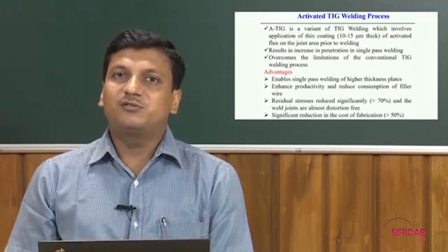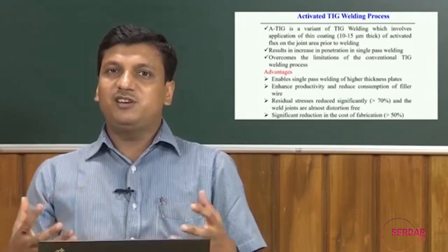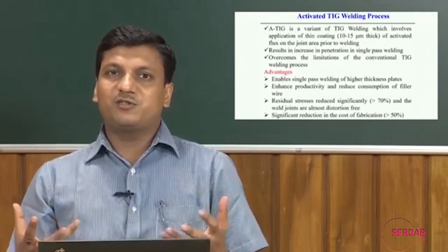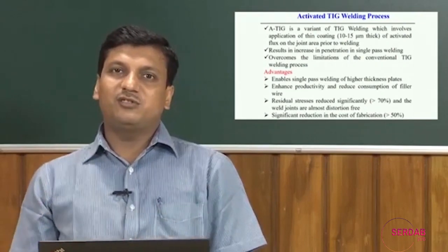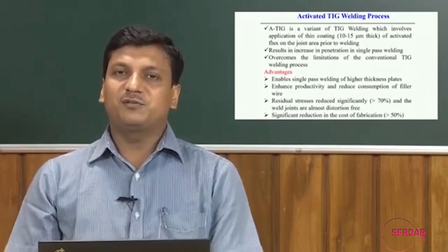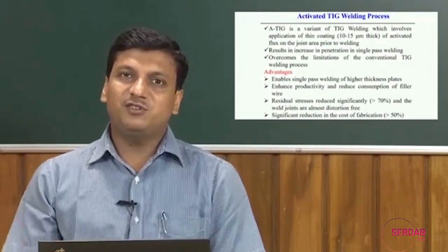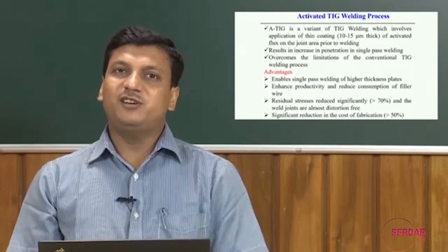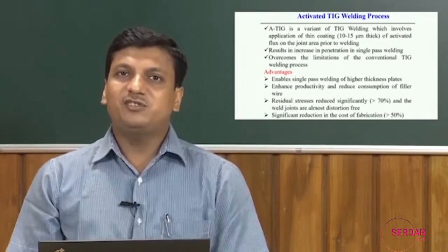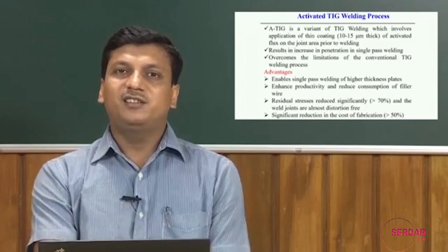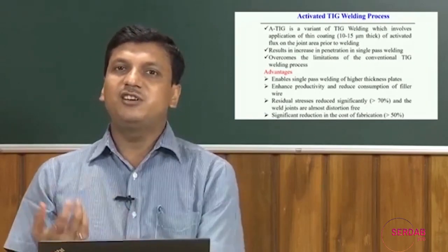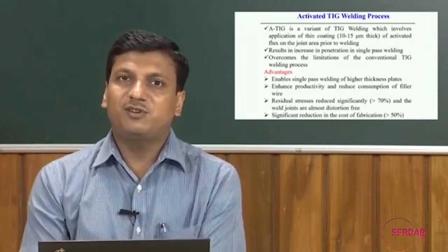more than 50% in general, because normally the TIG welding process is a low cost process as compared to the laser welding processes. Of course, with laser welding we can achieve high depth of penetration because of the highly concentrated heat, but even with TIG welding we can achieve high depth of penetration, only we need to modify it by including the effect of the surface active elements.